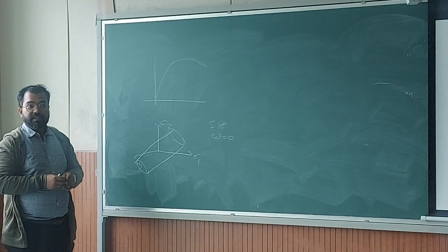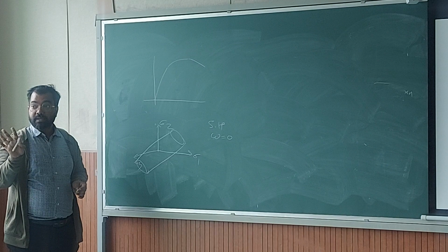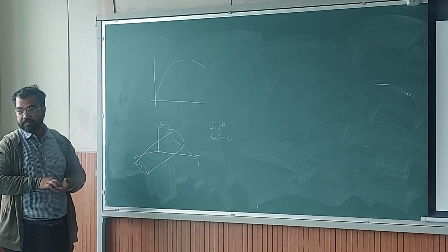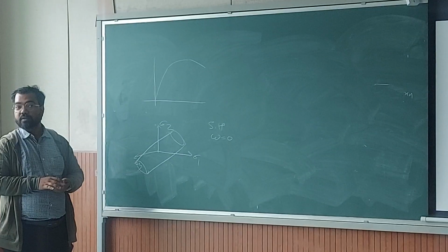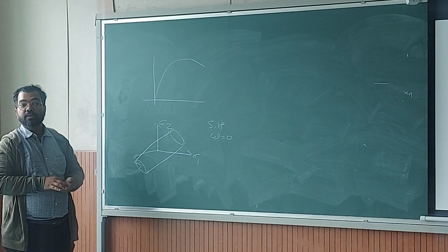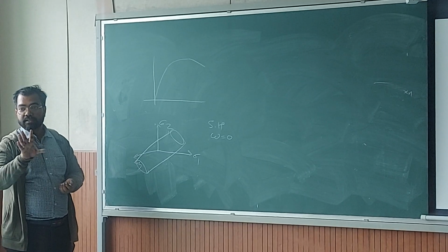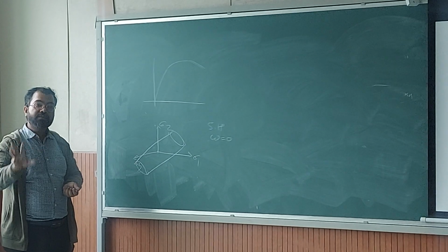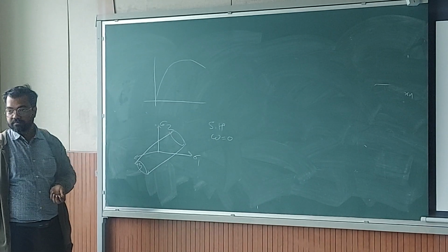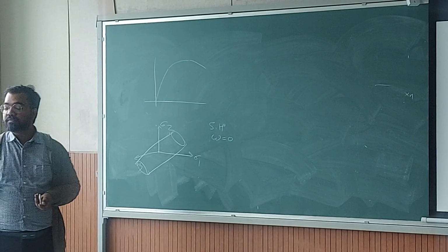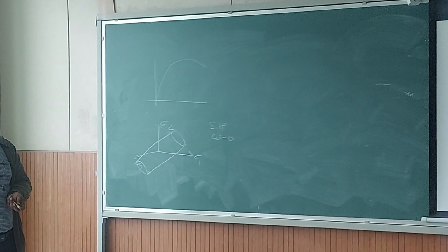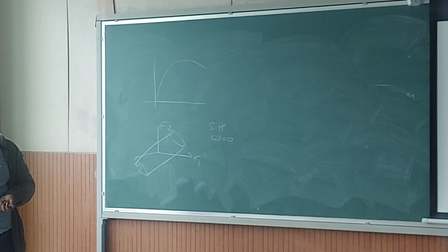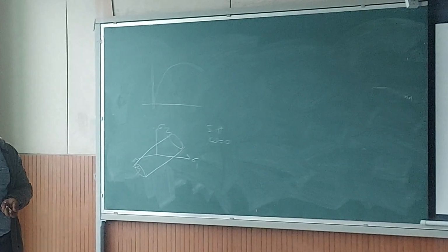Okay, so this kinetics can also probably be used for simulating the softening which happens in polymers, because the omega based formulation is not worried about whether you have voids in it or the entangled chains of molecules which are opening up. It is just taking care of the decrement in elastic modulus which is happening. So you can use this trick to simulate polymers also.